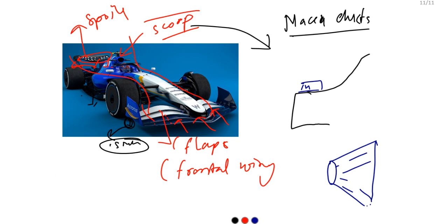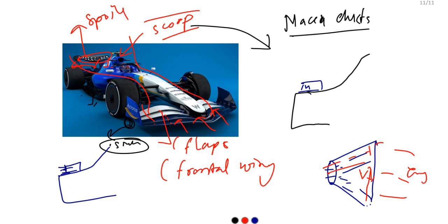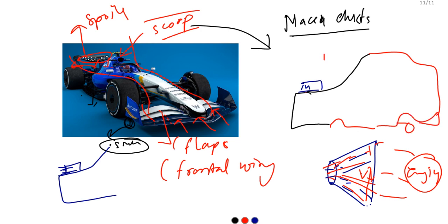In commercial cars it is placed at this particular point. So air is coming into this, high velocity air is coming in here. What will happen? The area is increasing, so the velocity is continuously decreasing. And one more important thing, this one opens directly into the engine segment, so it provides additional cooling as well as decreasing the velocity of air. At this particular section we can get downforce, not a lift kind of force.